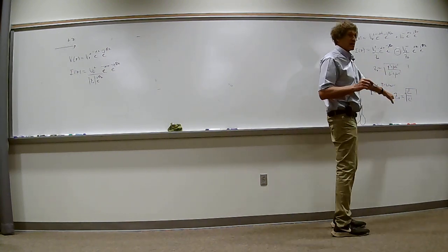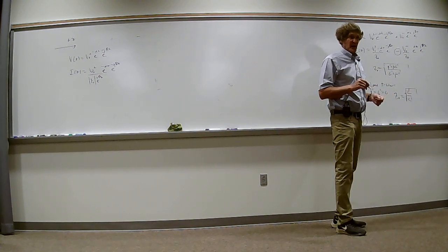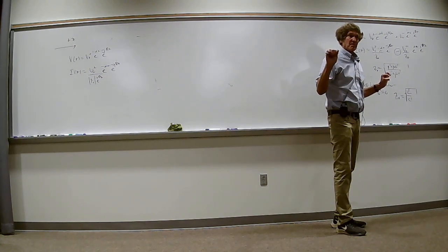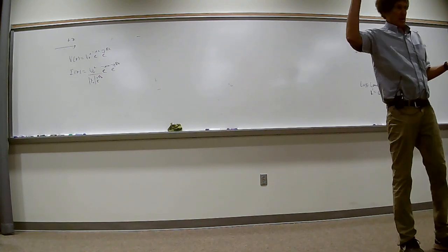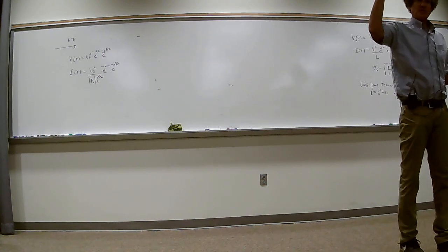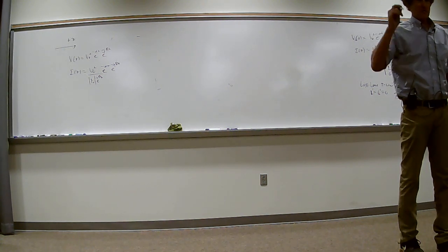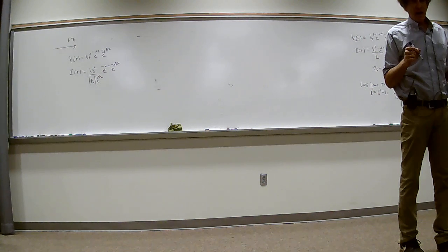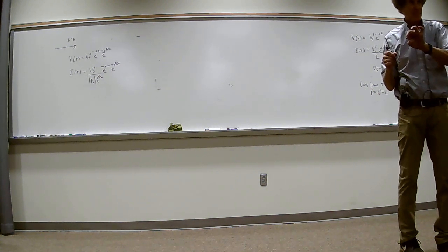Okay, so that's the characteristic impedance of your transmission line that goes to your house. Next time you look at it, see if you can find 75 ohm on it. How many have cable going to your house or your apartment? I guess some of you don't, which is rare, because I think they still have buried cable everywhere around here. Even Verizon with its fiber optic backbone still brings it in with a coax cable.